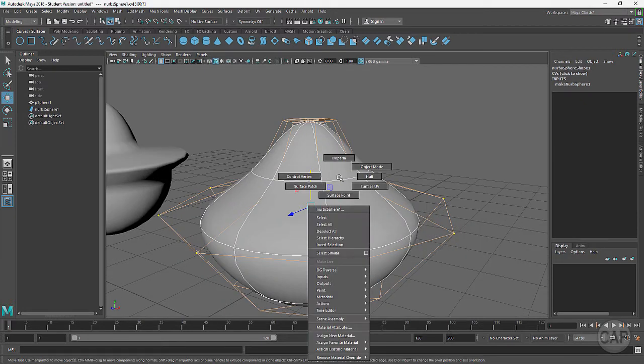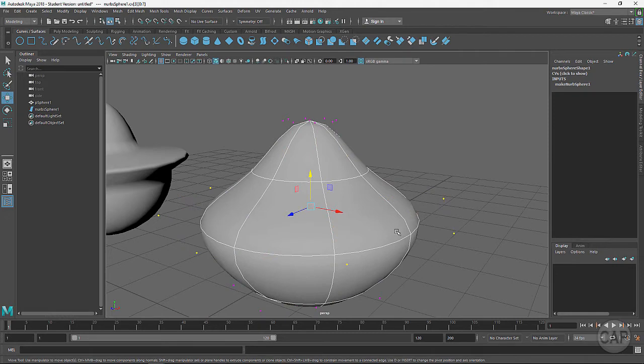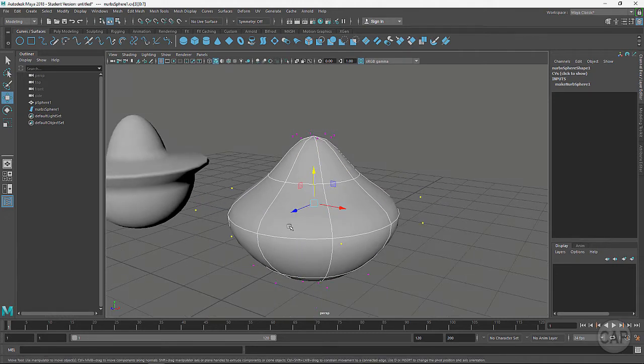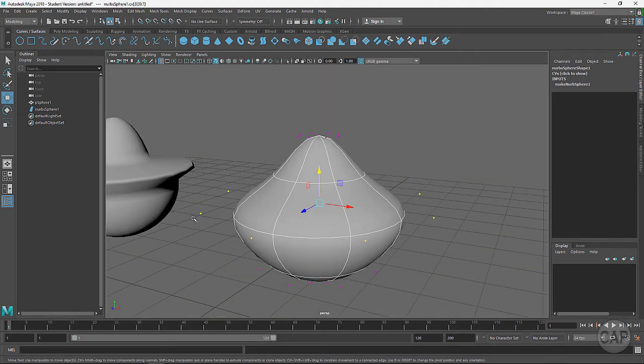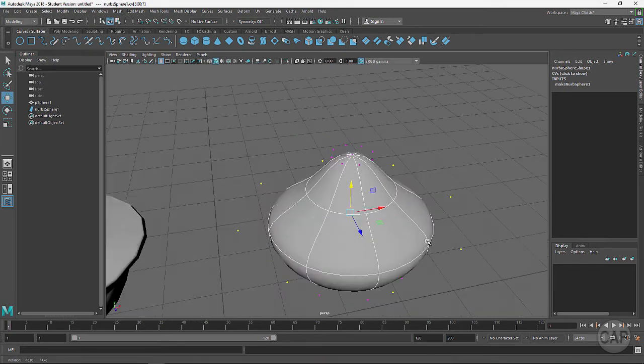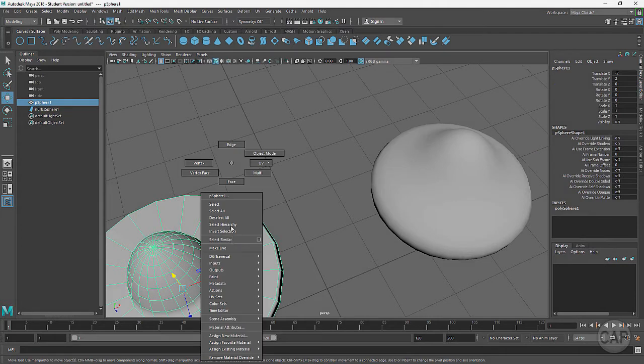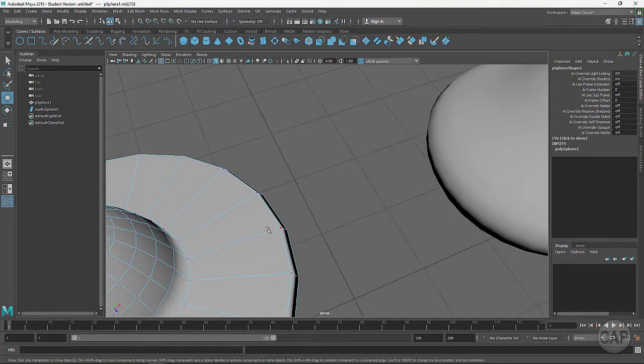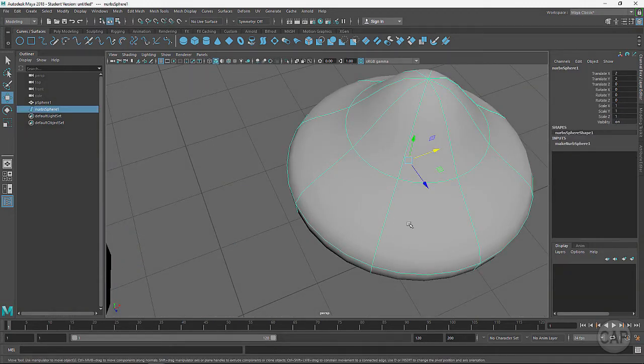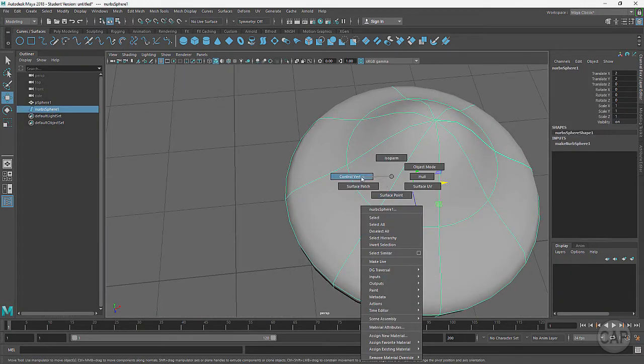And then let's right mouse click again and come over to Control Vertex. So you'll notice that these little control vertex, or CVs, are hovering outside of the model. So they're not like what we had over here with our vertex that were right on the model. Okay, these hover out here. This is part of that spline algorithm.